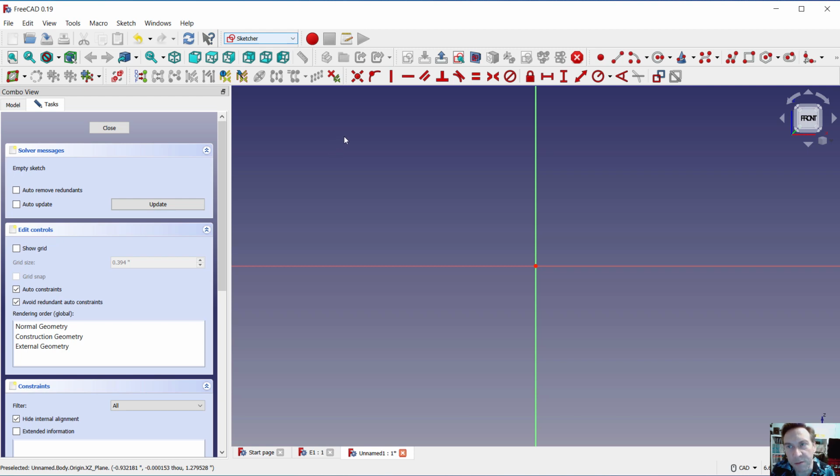But what we're first looking for is the rectangle tool. Now see here, there's additional tools. If you hit the little arrow there that pops out, we're going to be using those shortly. But let's go to the corner rectangle. Now find this point here. When the point turns yellow, when your cursor is directly above that little cross, click on it and drag it to the upper right. Click again.